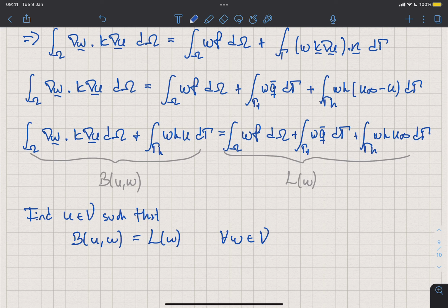It's just a choice. The choice is we just take functions from a space where those functions vanish on the Dirichlet boundaries because we just don't want to deal with reactions. You can choose to keep them as part of the formulation. I've seen that actually in a couple of papers. People actually keep them. But it is really not necessary, because if you really are interested in the reactions, then you can obtain them very easily by a post-processing step.